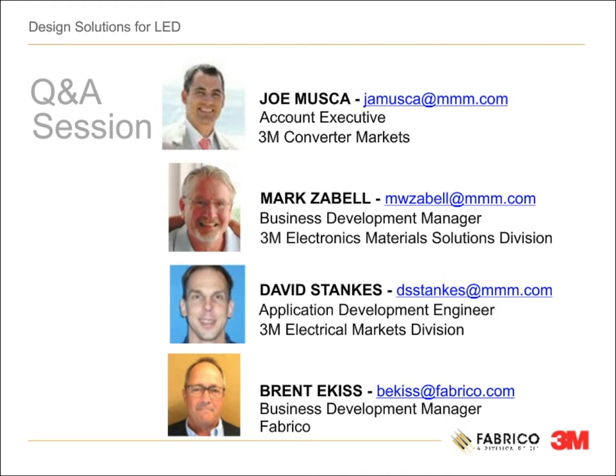Okay, great. All right, let's take a look at one more question here. What temperature can VHB tape stand up to? Yeah, this is Joe. I'll take that. So VHB will run continuously at 250°F, as an average, but it can take short-term spikes up to 300°F. Now, we do have some series of VHB tapes that'll go over 400°F, and the reason for that is mostly for going through a powder-coated oven.